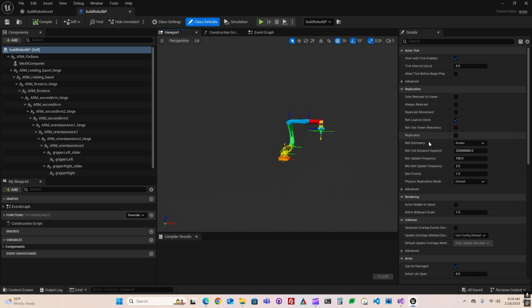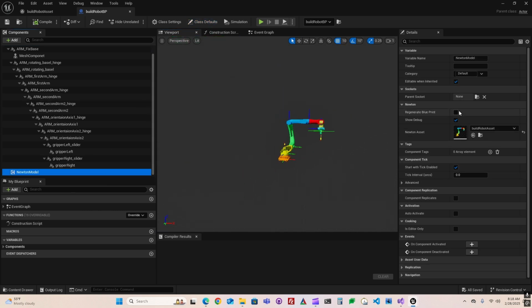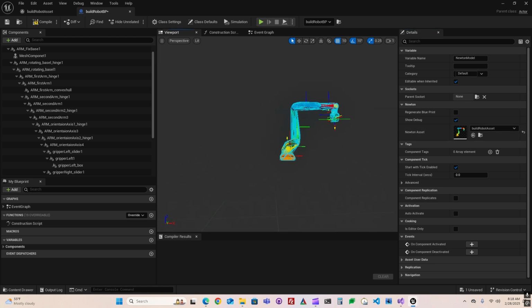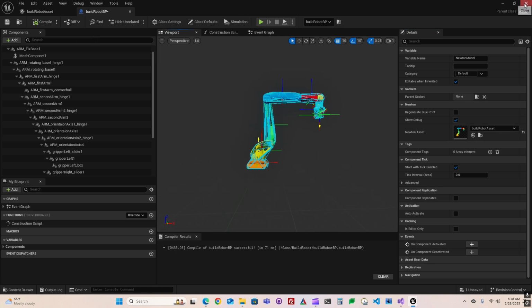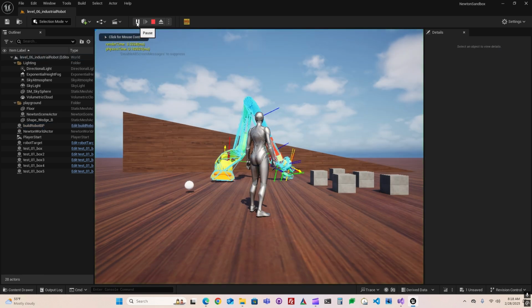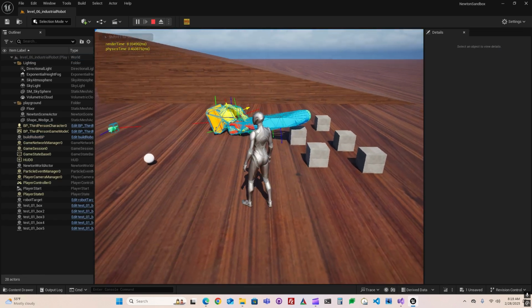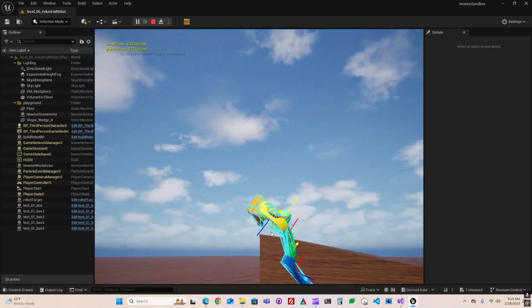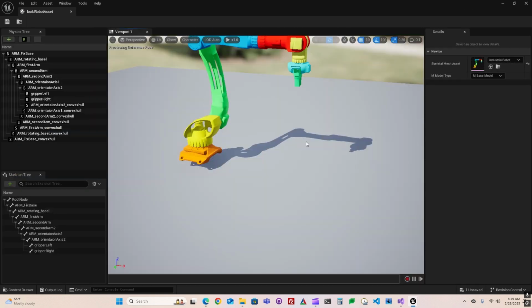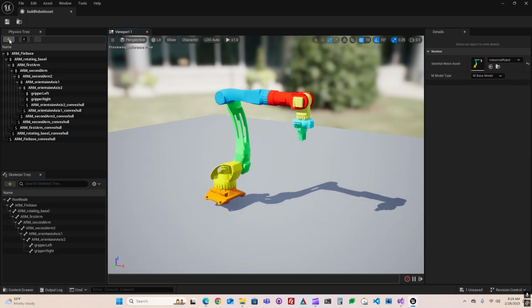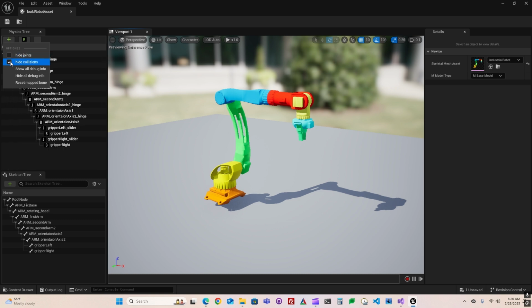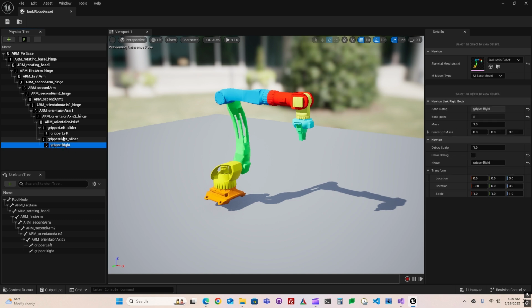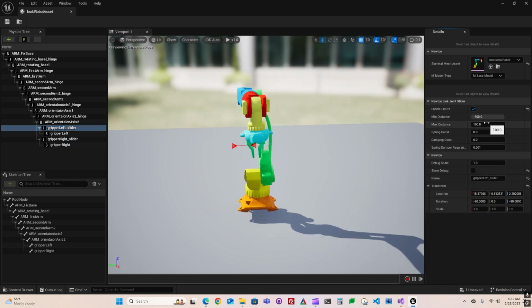The robot should now properly interact with the scene but will still behave like a ragdoll due to missing joint limits. Return to the Newton editor. Enable debug mode for better visualization. Adjust the limits for each joint. The gripper sliders should have appropriate movement constraints. The elbow joint has a limited range, so set limits accordingly.